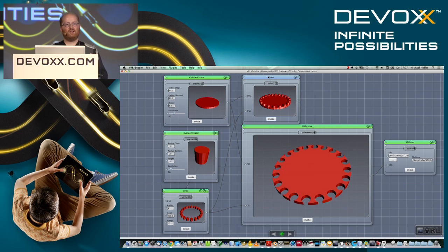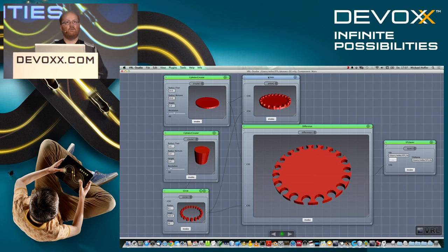And if you don't want one, like we did with the bracelet, it's assumed to be solid, but then we can tell the software to just print the outer boundary. And you can also say, like, fill it with 30% or 40%, depending on how stable the object should be. Yeah, that's basically how it works.